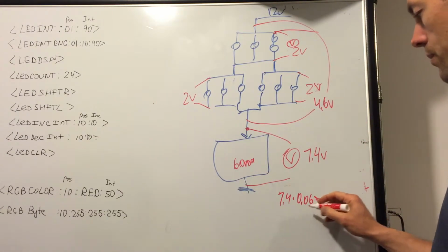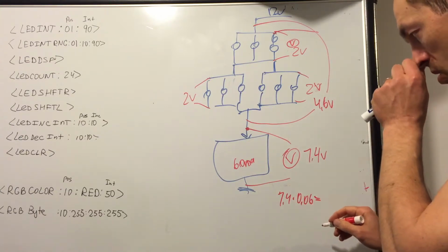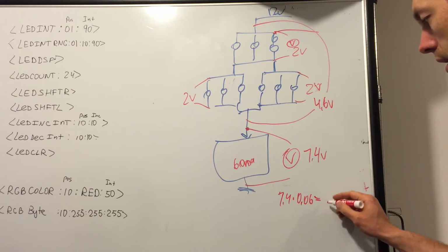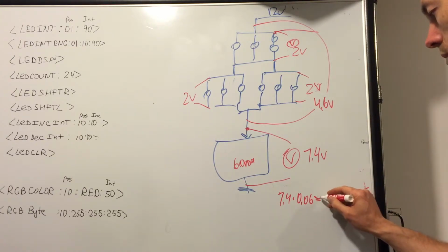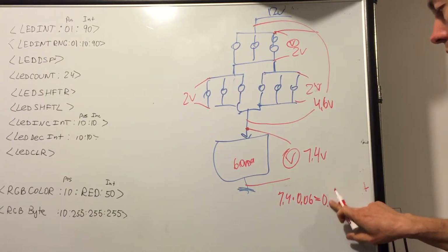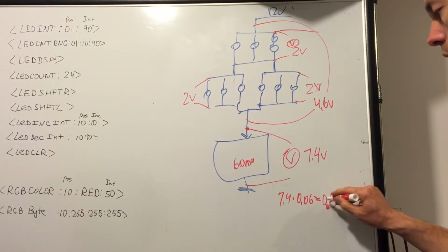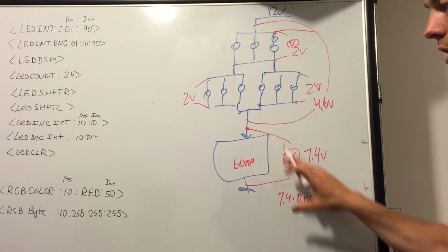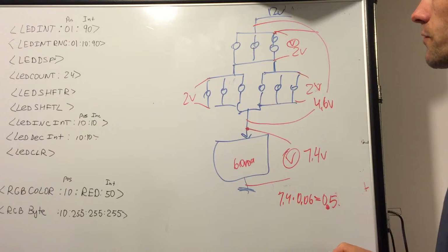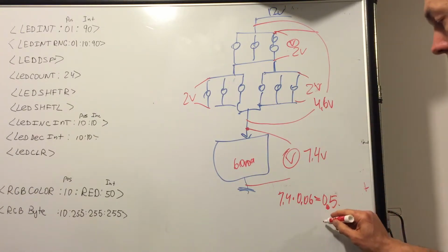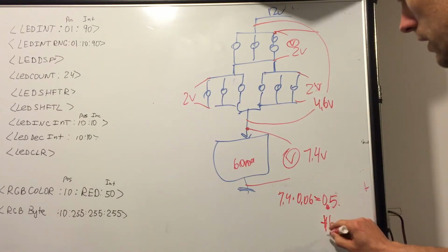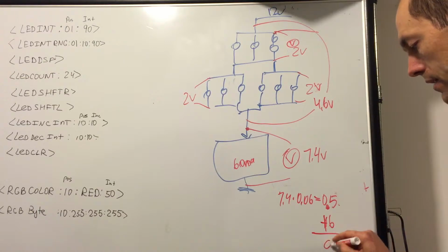I'm gonna approximate a little bit here. So 7 by 6 is 42, right? So it's approximately 0.042, a little bit more, I don't know, 0.05 volts. I'm sorry, watts. So this is 0.5 watts dissipation of heat, the current produces the heat on this circuit for one channel. So now we have 16 channels. So multiply this by 16. Yeah, multiply by 16. The total number we have is 8 watts.